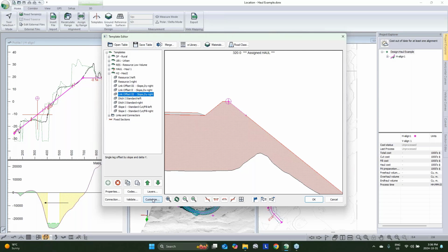Now, if this is something that I plan to use over several templates, or maybe I want to just make it easier to make adjustments, for this one, if I want my berm height to be the same on the foreslope as the back slope, and I want to control it with one parameter, then it makes sense to throw it all in a single component. And we won't make it really more complicated in terms of geometry or logic, but we'll just make it easier to work with.